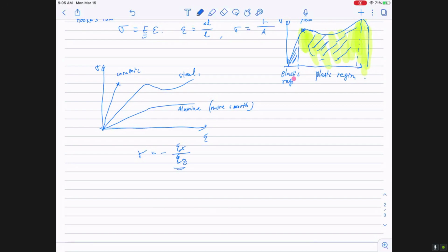And this generalizes for super elastic materials, for example elastomers, elastic rubber kind of structure. For an elastomer, we put the Poisson ratio at 0.5. That's super elastic, close to 0.5.